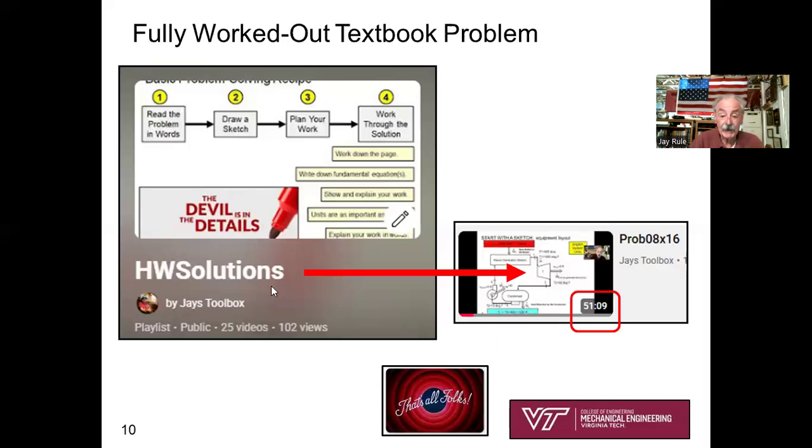Well, that pretty much covers it for the condenser. And so you see, all we did with the condenser was just apply the first law of thermodynamics, open system, steady state, steady flow, to solve for the heat transfer. Hope that helps. And let's see, we have one more component to go. That'll be the feed water pump. And that could be the trickiest component to analyze. So please have a look at how you analyze the feed water pump.